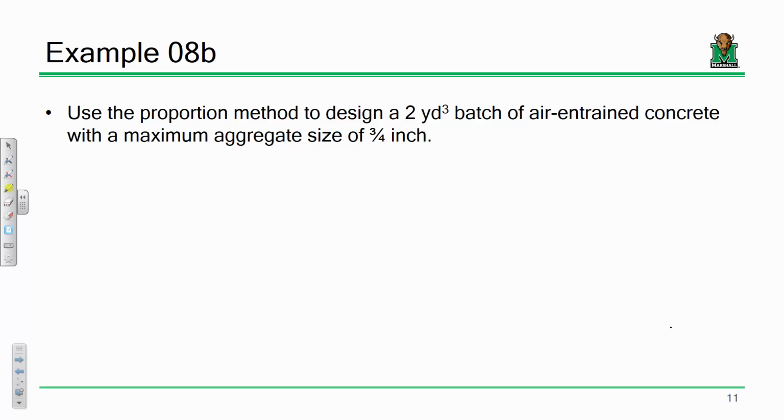Four main ingredients: cement, water, gravel, and sand, right? So this is how this is going to work. We use our three key pieces of information at the very beginning: our target compressive strength, our data about our aggregates, and our intended use. Now, we're going to use that data to determine how much cement needs to go into it, how much water, and how much coarse aggregate. And we're going to use those three, and then back calculate how much fine aggregate needs to go into it. There's no real reason why we're back calculating that one. It's just the way our procedure goes.